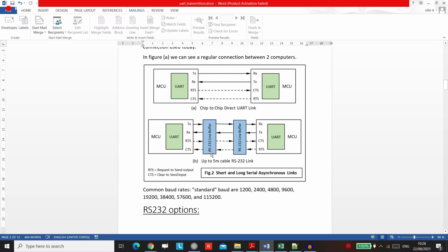The physical layer will be on RS232, and this just means that the UART communication is transmitted over different voltage types. The UART communication itself is just a protocol for the communication: how the frame is set, the frequencies, the baud rates, and everything. It doesn't include what voltages we're going to use, or how the data will change according to our board that we're developing on.